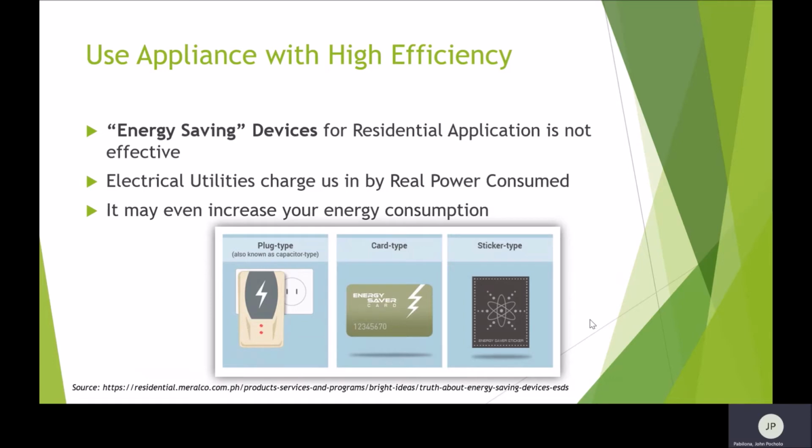However, capacitor banks or other power factor correcting devices in commercial and industrial applications still have their own benefits since they have large motors that require kVAR and different billing calculations, which include penalties and incentives related to power factor.